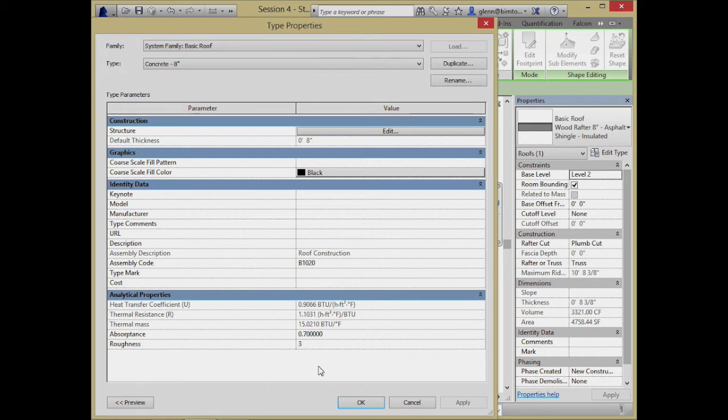Really, one of the requirements, even in building a house these days, the Title 24 requirements, is that you tend to have a certain amount of thermal mass in the house so that it will store and slowly re-radiate the heat, as opposed to just having it all flow back out very quickly through the walls. So those things kind of work together. Let's think about how we can actually get them to work together. Okay, but let's go ahead and choose some material for the roof.